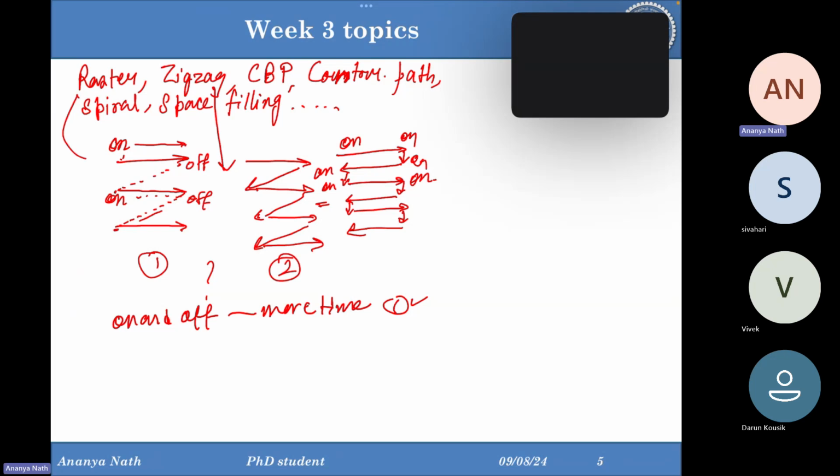And when you are turning off, there is an inertia again at the last position. There is an inertia at the on position. There will be again one inertia in the off position. Again moving back, again one inertia here, one inertia here. So because of the inertia, there can be excess material dropping out from the nozzle or lesser material. Both can be the case.